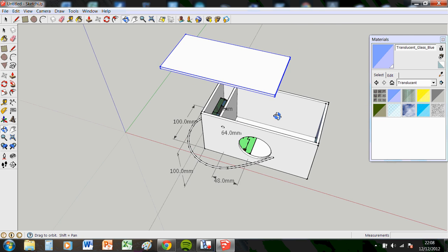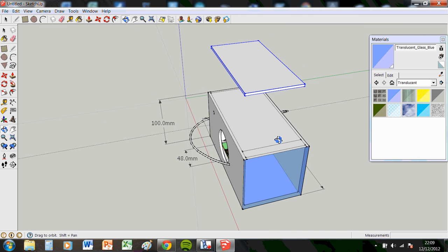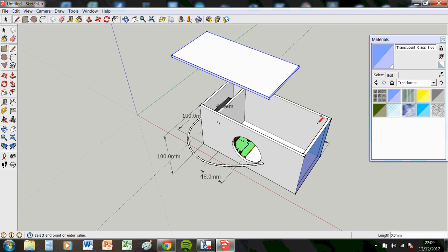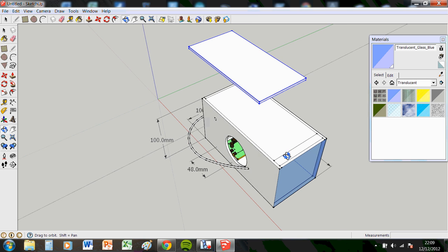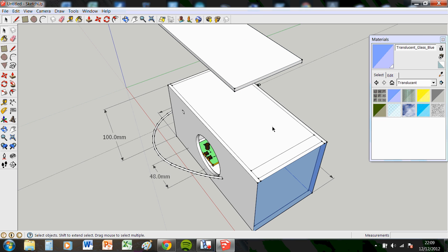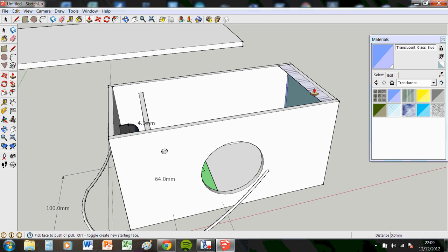Now I really want you to do every level of detail to get a good grade. If you're going to make little shelves for instance, like this, where you would screw into, do that. The way I suggest is maybe draw a little rectangle, just draw a line across. You'll find it fills in the whole top, but that's easy to get rid of. Just click the bit you didn't want and press delete. There we go. Obviously I'd need to pull that down 4mm, so type 4.